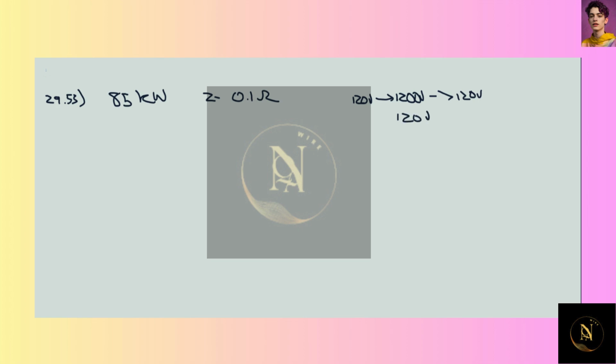Okay, and we assume that the efficiencies of the transformers are 99%. Okay, so first let's figure out P lost for the first case. So we have P out is given by V out times I out. Sorry, this is V in the line times I in the line. So if we're trying to get 85 kilowatts of power at 120 volts,